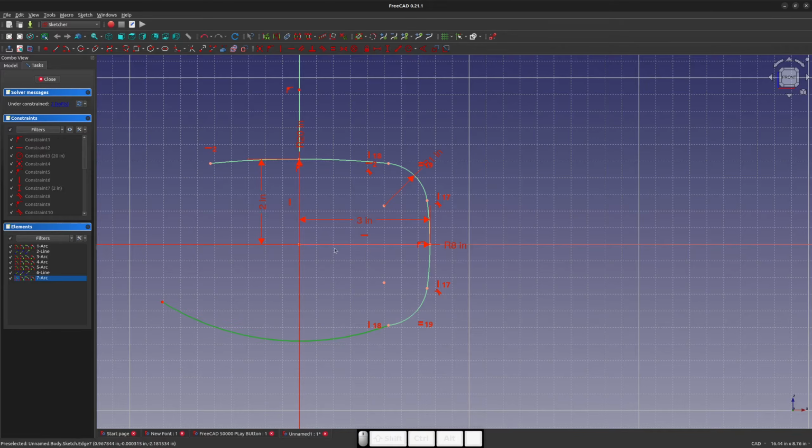So we're going to say E for equal there, and then V for vertical, and we don't need to add any more dimensions, right? We can fully constrain only with constraints based on what we have. We're going to say between these two, T for tangent, E for equal, between these arcs, we're going to say H for horizontal. Now we're going to go with an arc here.